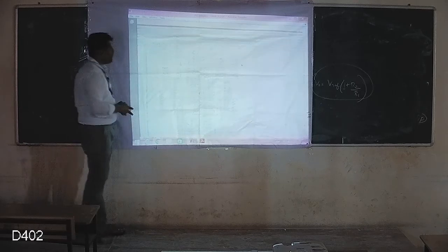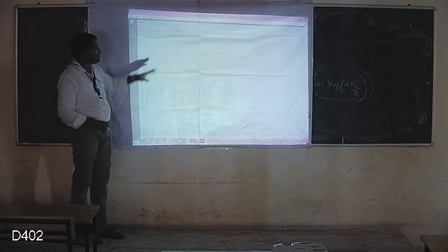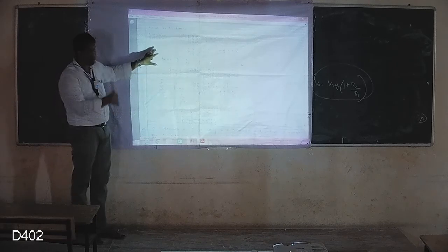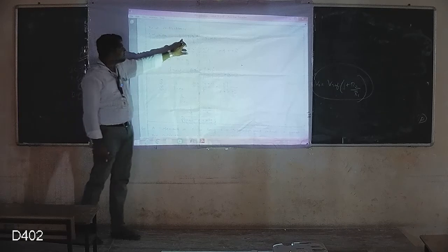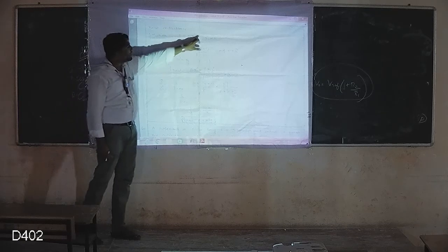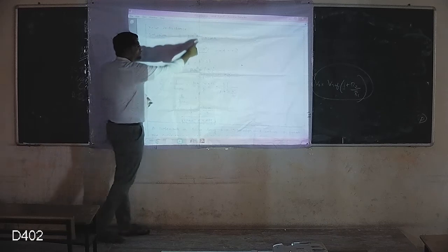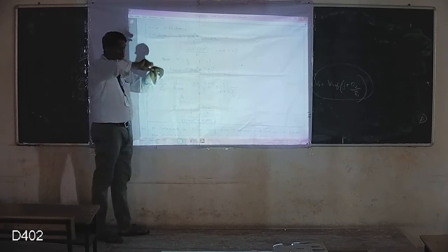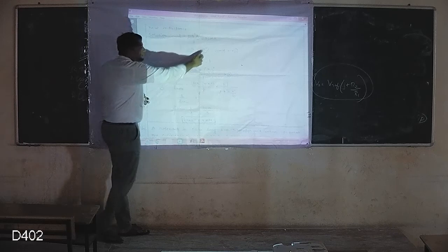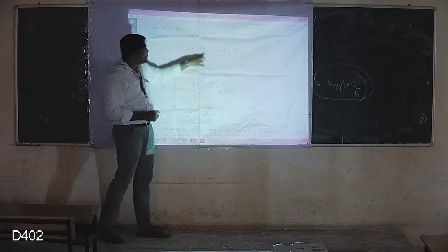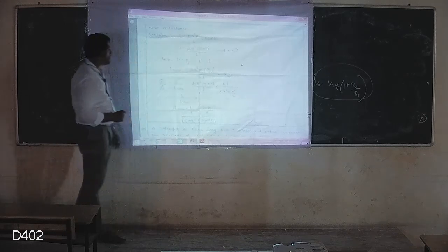Therefore, with the solenoid as an important material, we know the inductance of a solenoid is mu n square A by L. That is given as 20 millihenry. Since the solenoid has a circular cross section, the area becomes pi r square. So this amount is equal to 20 millihenry, equation number 1.